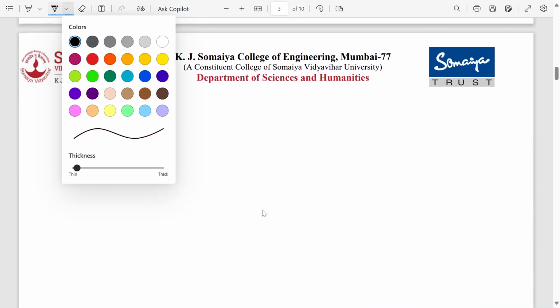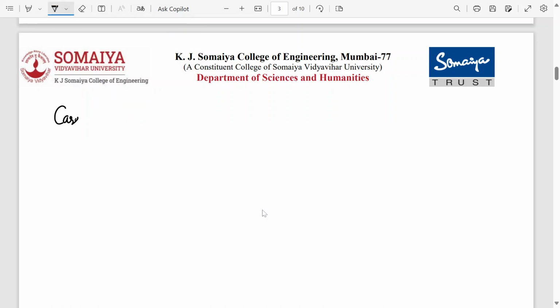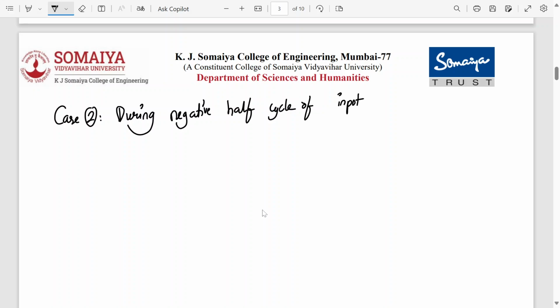So case number 2, I hope you are following. During the negative half cycle of input Vi, diode D1 is reverse bias, therefore it is off.